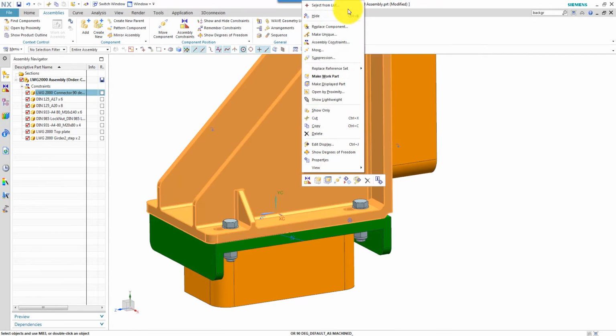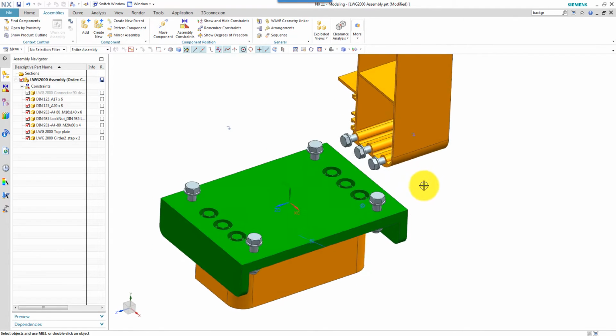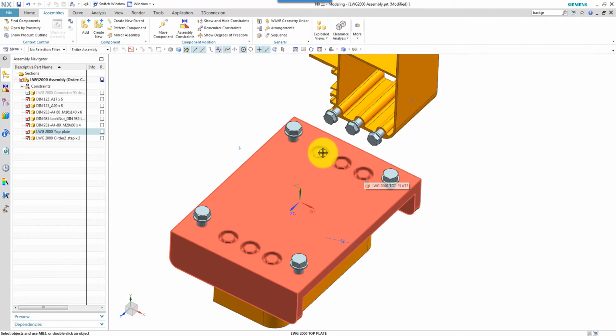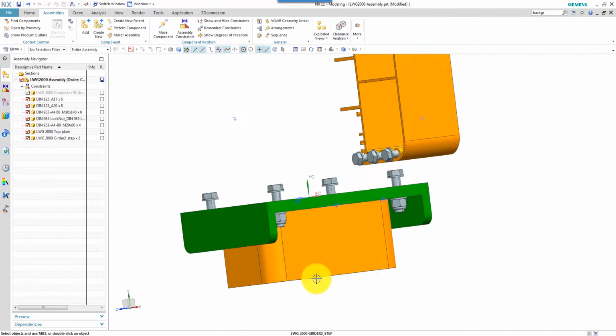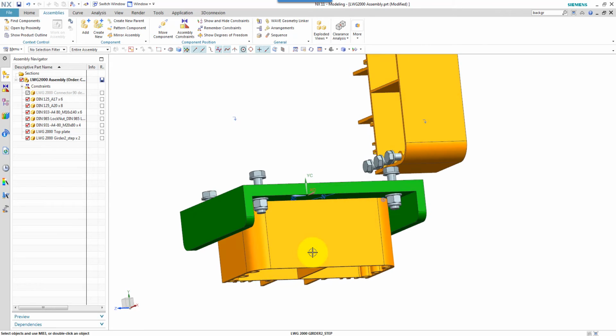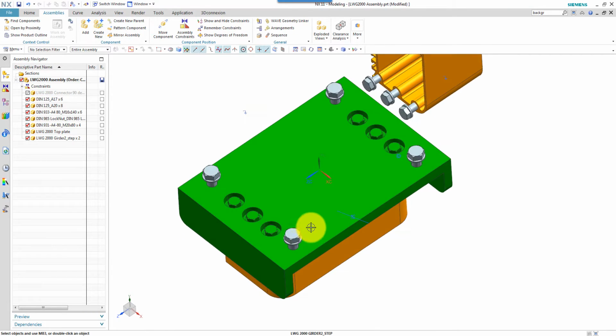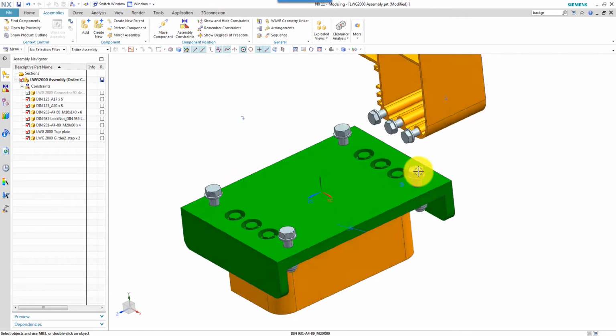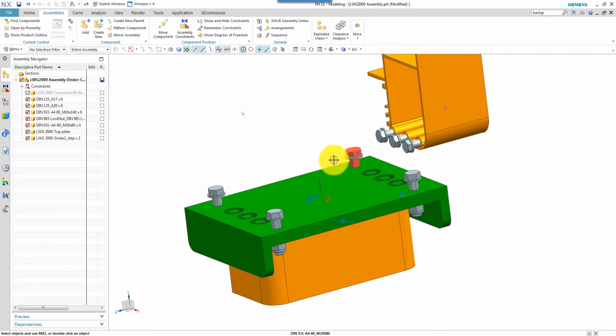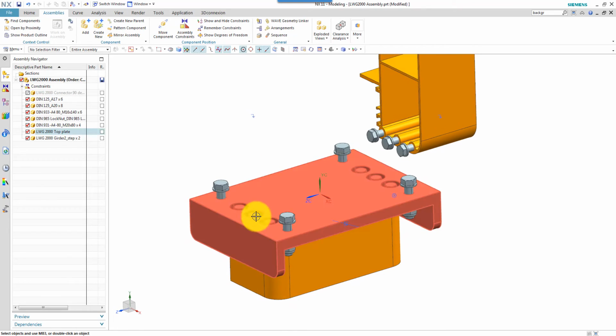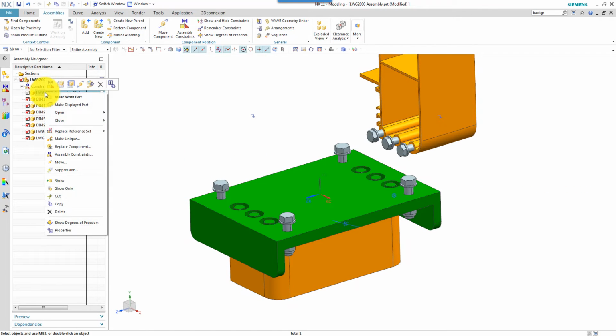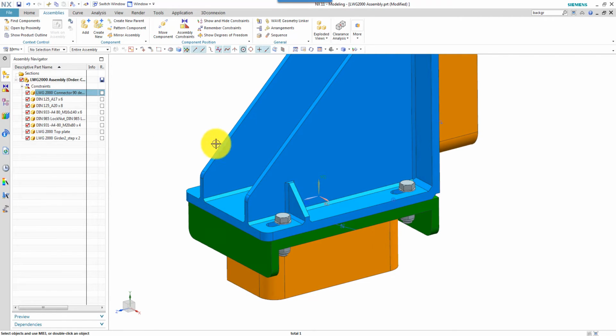If we hide the connector, you can see that the same 6 bolts are used to connect the top plate with the vertical girder. And then we have 4 M20 bolts, which connect the top plate to the, let's have a look at it, to the connector.